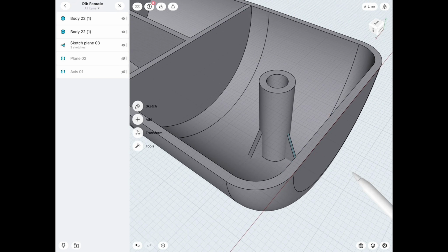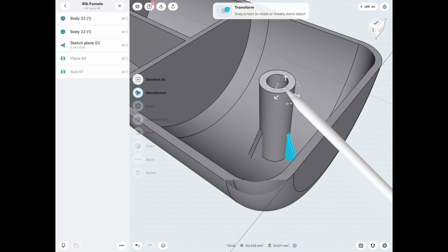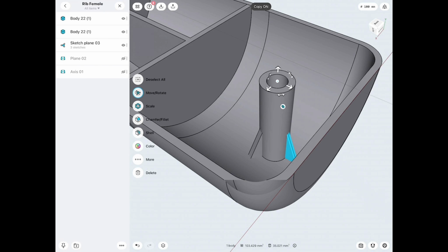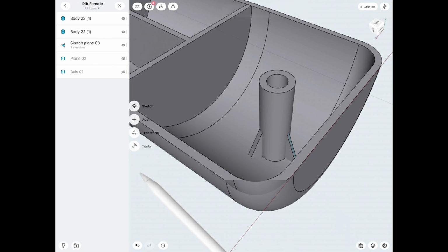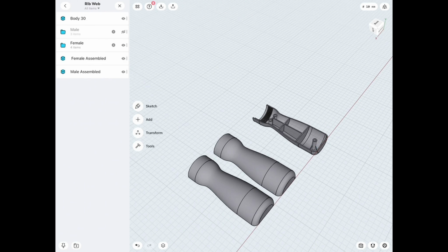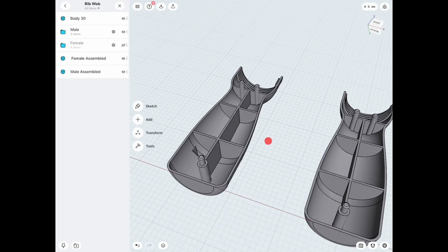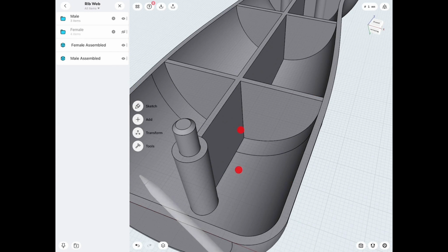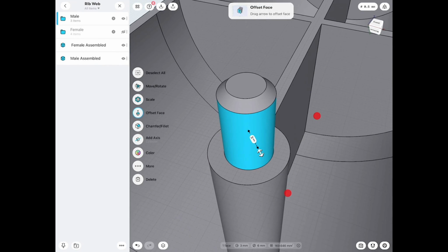Very good. And now I can go ahead, double tap it with the 3D widget here, move maybe to the upper edge. You see it's a cylinder, finds the center, make a copy, and start rotating it. So that's the way then how I created those elements. Very easy. I would like to show the other one. It's just the opposite part. There I have the cylinder, and then I extruded a pin. And to make the sliding a little bit better, I chamfered the top part.